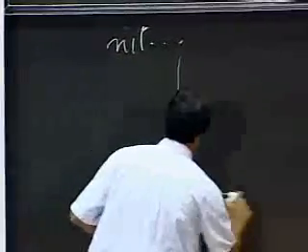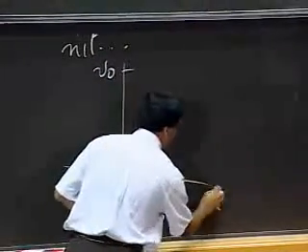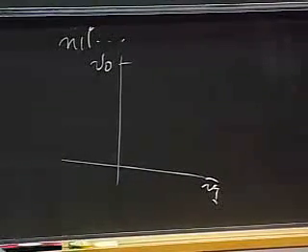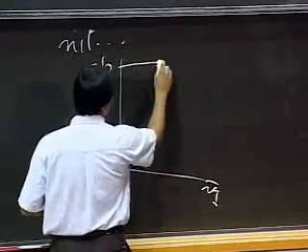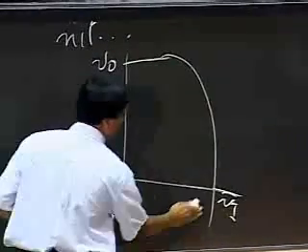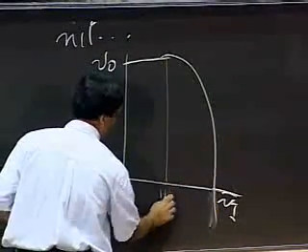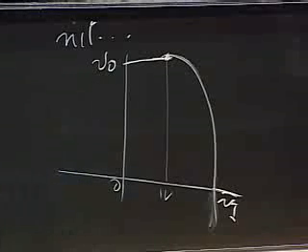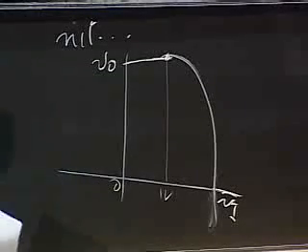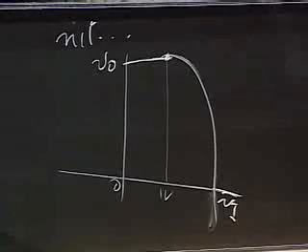In the curve that I showed you, in the mathematics that I gave you, if we just go by the math, what I'm going to show you now will distinguish a mathematician from an electrical engineer. A mathematician would have taken the curve and plotted it like this. This is 0. Mathematically, that equation says that starting here, this current simply goes down, kerplunk. But if I told you that this dependent source is a practical device that I have physically built, and I also say that it's a passive device, in other words, that it cannot produce power, it's like a little resistor. It doesn't produce power.